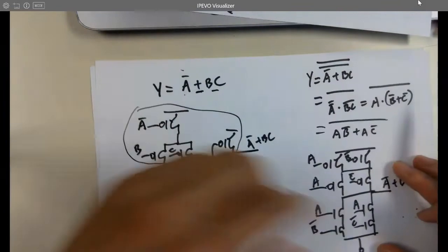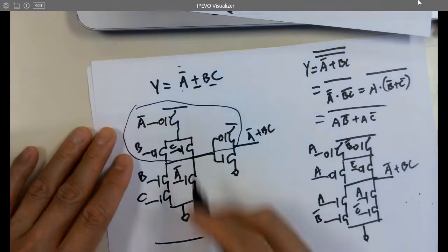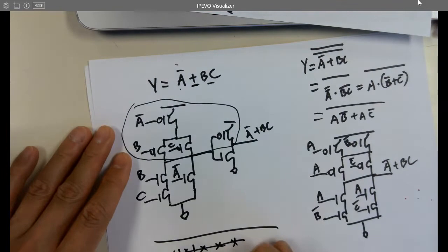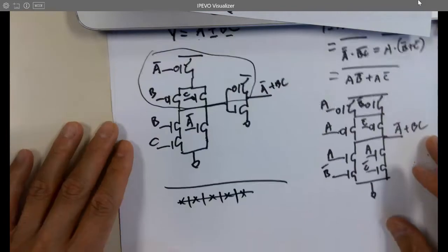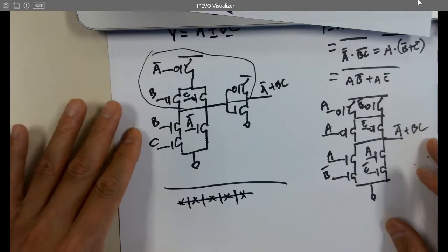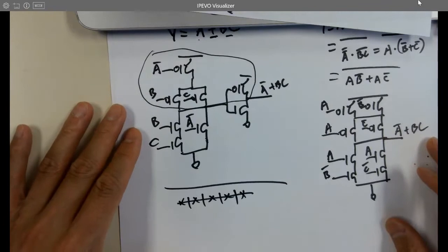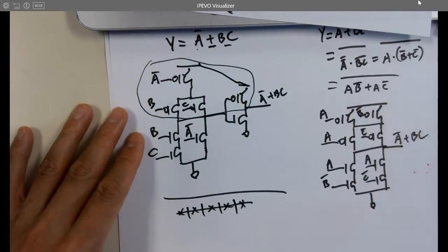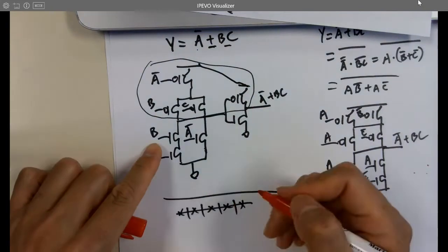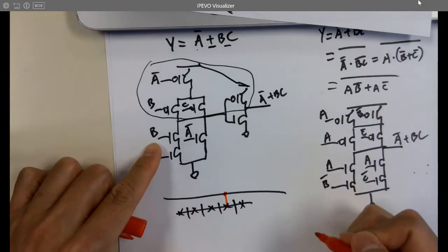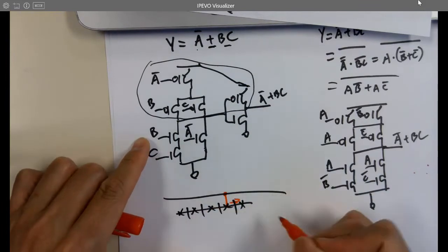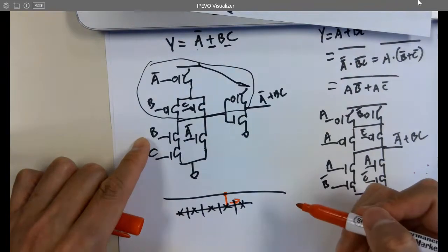And we can make this one into this, right? But can we convert this one into something in one line? Let's try the PMOS really quick. 4 transistors, 1, 2, 3, 4. Can we convert into one line? These two are both VDDs. So if you want to convert into one line, you have to introduce the VDD here, because this becomes the inverter's PMOS, and this becomes these PMOSes.